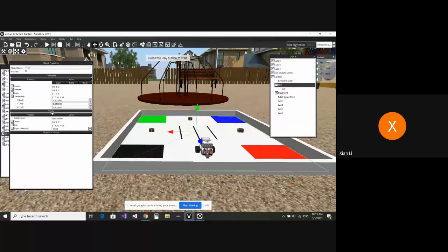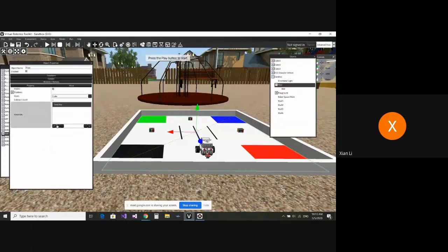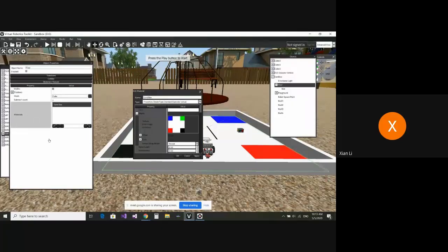And then we have collider added, and also a texture. So the texture is what we are looking for. That's the map we added to the floor. And then what you can do here is press the pencil button here at the corner. You're going to bring up another window called Edit Material window, right? And these are the options you can play with to edit the material.